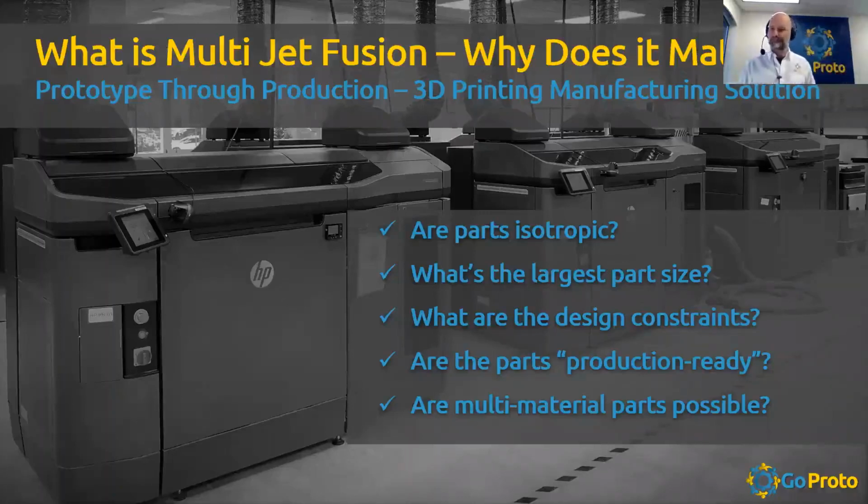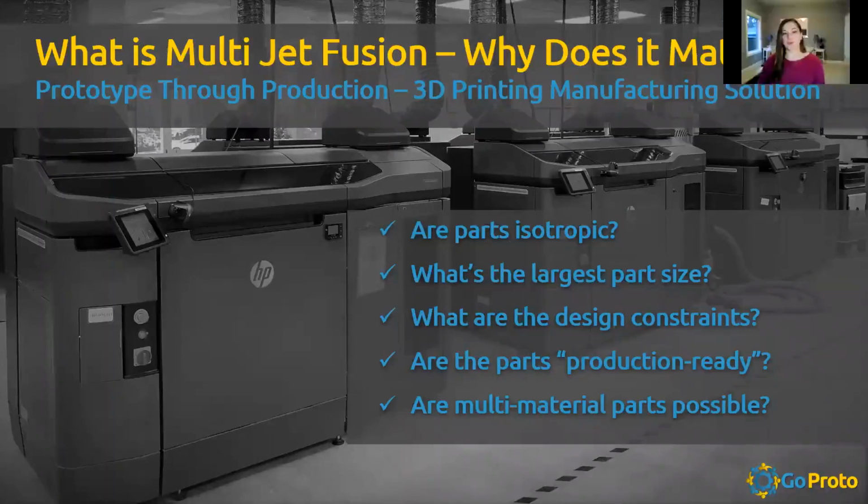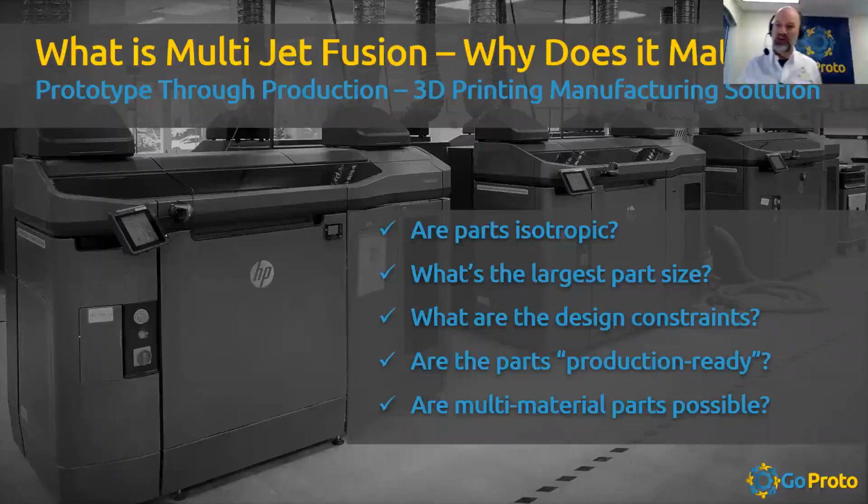But Jesse, one question that just came in that I think is relevant here in terms of design consideration and multi-material is, can you get a dual durometer TPA in one build? Great question. Same at this point, it is a single durometer, and it is 90. But something that's really important is that we're all used to thinking of durometer in terms of how far your thumbnail will push into it, how soft it feels, and that usually is in an injection molded part that has a solid wall, because that's how we've been able to produce it.